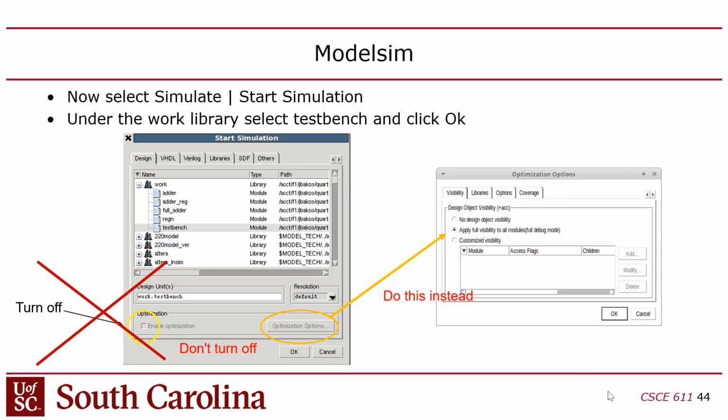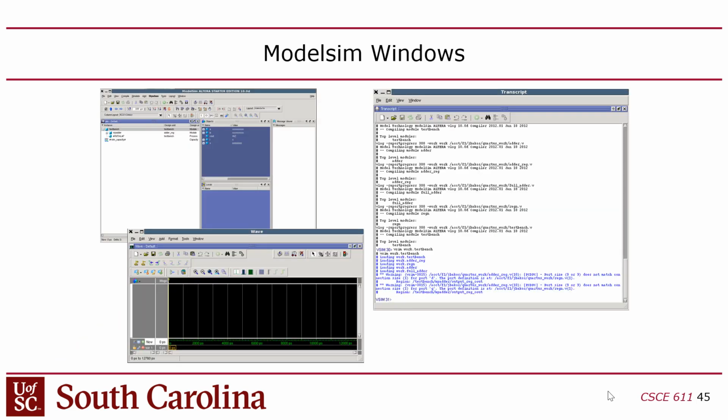All right. So we talked about Quartus, and then I demoed Model Sim. Now, unfortunately, I can't directly simulate this design in Model Sim. I mean, I can, but it's not practical. Anyone know why? Yes? It doesn't have all the LEDs and switches and buttons? Yeah, that's part of it. If I simulate this in Model Sim, I need a way to also simulate the inputs. Now in this case, this design doesn't require any inputs except for the clock, right?